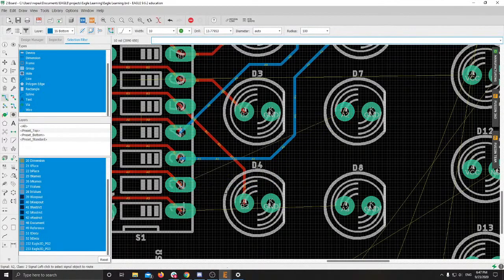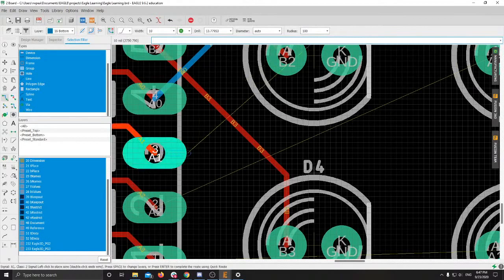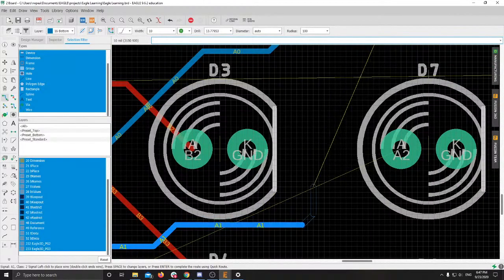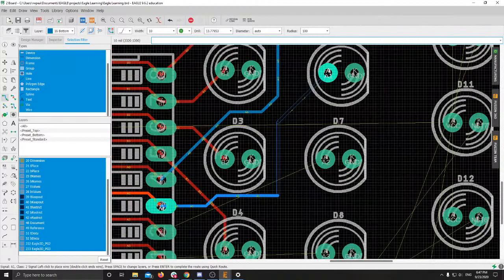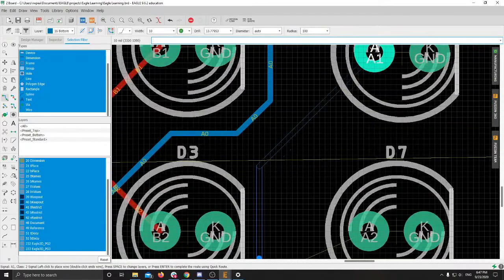And again, I did something bad here because this A1 isn't perpendicular, so I'm going to reroute it to be. This is where you sometimes have to get a little bit clever. I'm just going to do a little cross right there before coming over again, and then reroute it. And then again, this one doesn't want to cooperate, so sometimes you have to help it out a little bit.